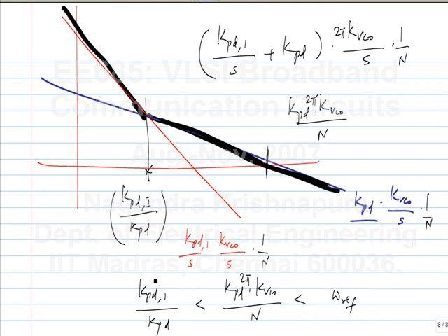So this first condition ensures that it is stable, that the slope is 20 dB per decade at the 0 dB crossing. And the second condition ensures that there is high attenuation for the reference feedthrough. And you can have additional poles here. So let me call it P2. Let's say you have one additional pole, in which case you should have this to be less than P2. P2 should be beyond the unity gain frequency to ensure stability.